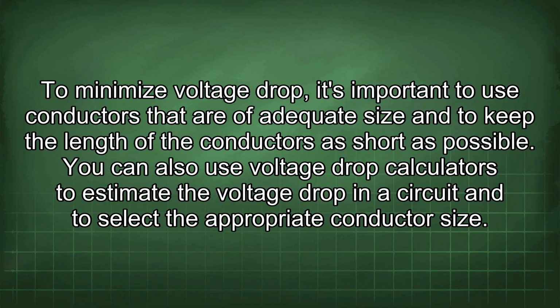To minimize voltage drop, it's important to use conductors that are of adequate size and to keep the length of the conductors as short as possible. You can also use voltage drop calculators to estimate the voltage drop in a circuit and to select the appropriate conductor size.